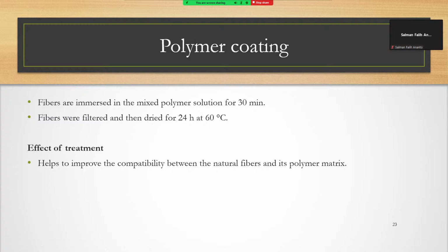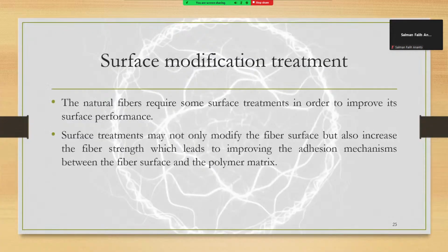Despite the importance of surface treatment, there are a limited number of approaches used to tackle this challenge, due to the lack of availability of surface treatment equipment. The most available surface treatments are plasma treatment, vacuum ultraviolet irradiation treatment, ozone treatment, corona treatment, gamma ray treatment, and laser treatment. These are the most commonly used surface modification treatments. But these treatments are very costly.